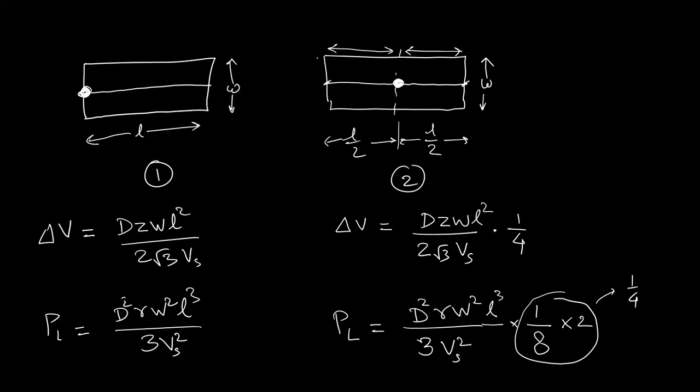So in planning study, this is used. Now this is indicating that putting the substation at the center point is giving more advantages compared to placing the substation at the corner of the service area. So this is from a technical point of view, but there are other non-technical factors that will also be there.